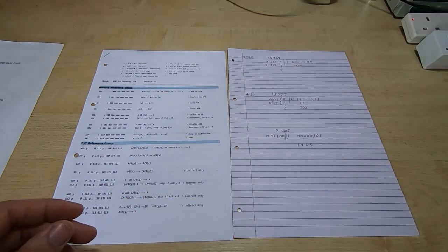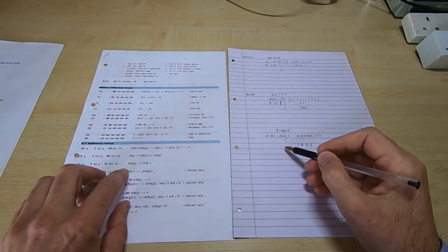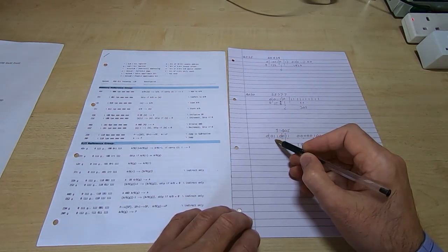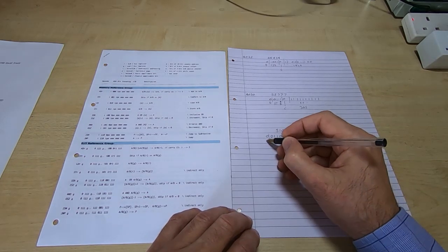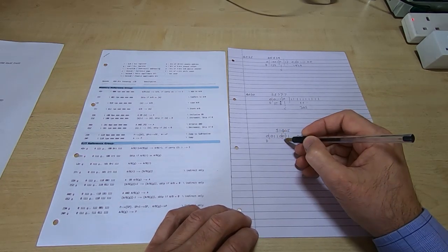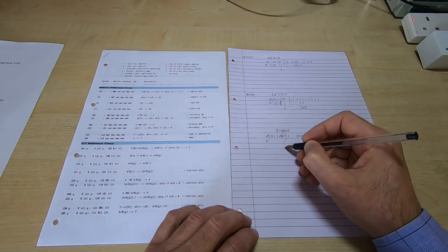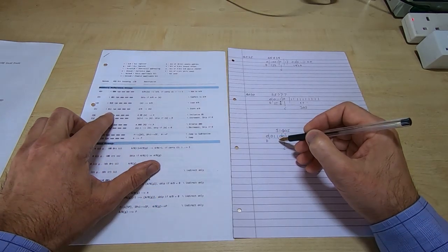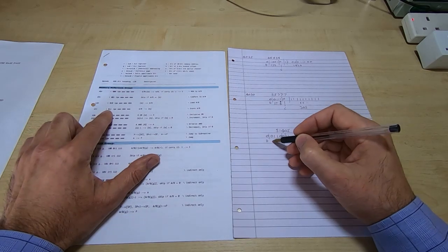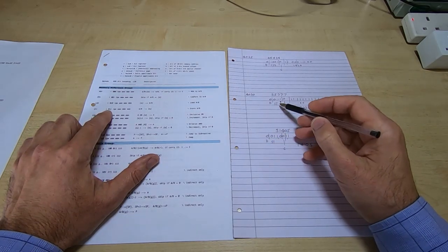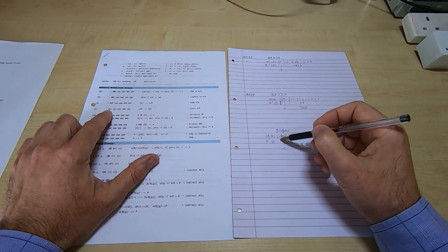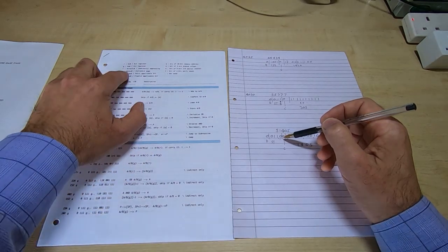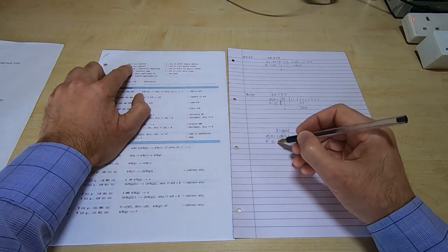But if we decode the rest of the instruction to see if it fully matches the listing, then again, if we pull out the middle 4 bits and try to identify what this particular instruction is, firstly we know we're using direct addressing and we're on the current page, and that just leaves these 3 bits to identify the particular instruction, which should be 011, which again it is, and it is a store instruction as was shown here, and the value after, however, is a 0, not a 1 as it was in the captured data. And if we look at that, that means it's store A.